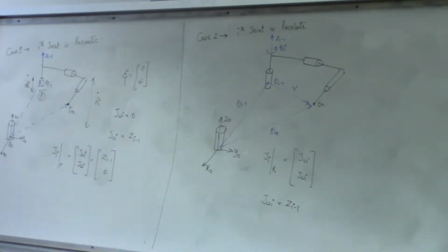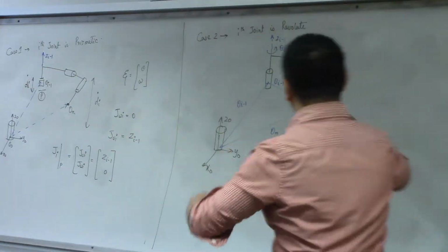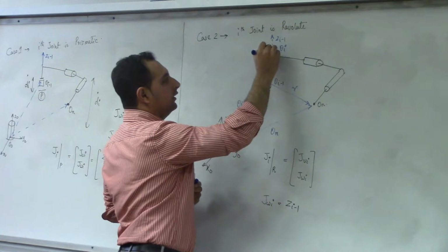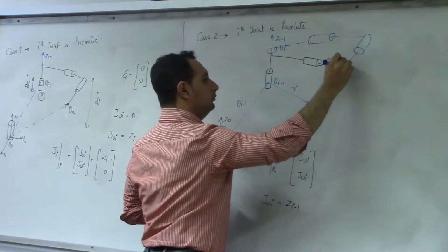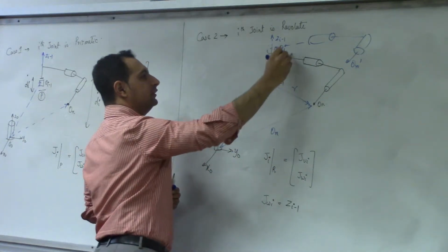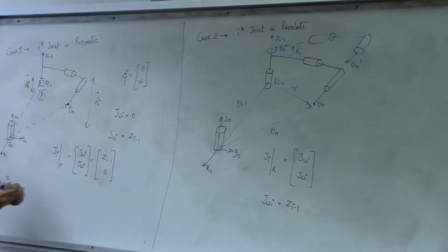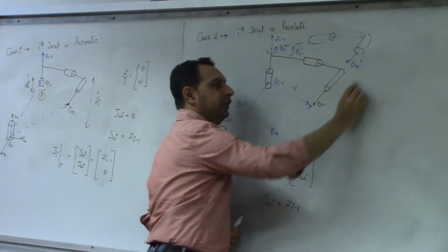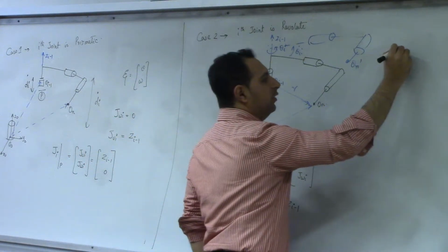Okay. Now, will there be any linear velocity or no? Yes. Right? A revolute joint creates both angular and linear motion. So when this is moving, the point is turning. So this point will exactly move. It might move to something like this. Right? When it's moving like this at a theta I dot, right? So it can move like that. So when it moves, obviously the coordinates of the point have changed in some time. So if you differentiate it or divide it by that time, you get a linear velocity. So in this case, we need to find what is JV.